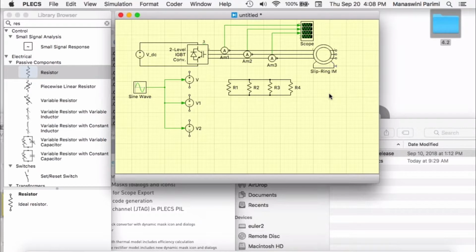Okay, so it is also now possible to drag more than one connection segment at once. So for example, if we had something like this and we select these vertical components, now we can choose these segments and drag them all together to left or right. This will move one segment of every selected connection, always the one closest to the mouse, like so.